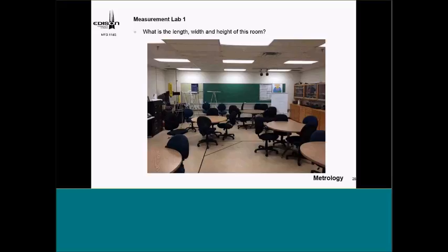So in other words, you've got to count how many times you overlap it, or you mark it, and you go to the next one and mark it, next one and mark it. I actually have people that will literally count the blocks, and they'll measure the blocks. So how do we make mistakes there? How about computational mistakes? There are math mistakes, etc. The other area that we'll get in trouble, they don't measure to see if the room is parallel or square, perpendicular. So again, I'm trying to show them how we make mistakes in measurement.